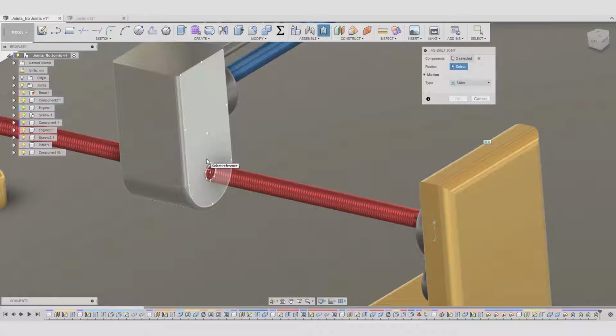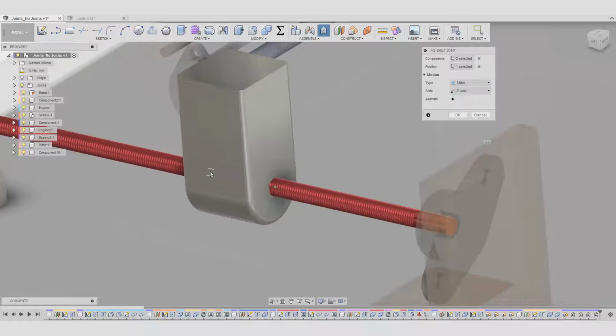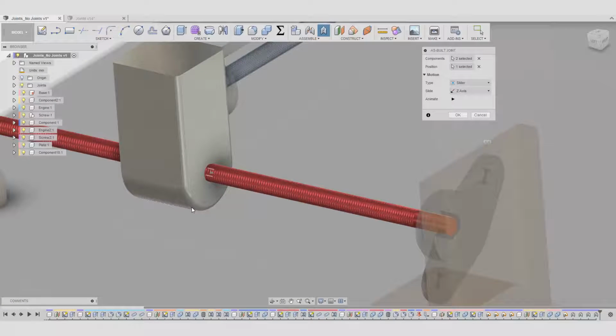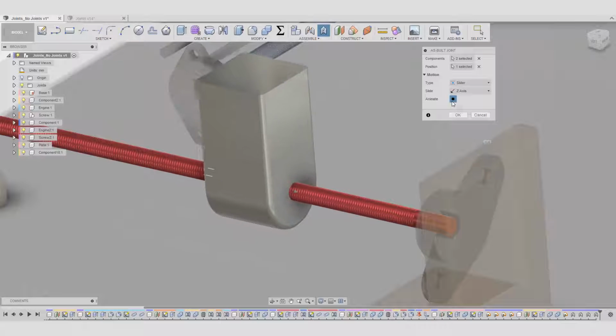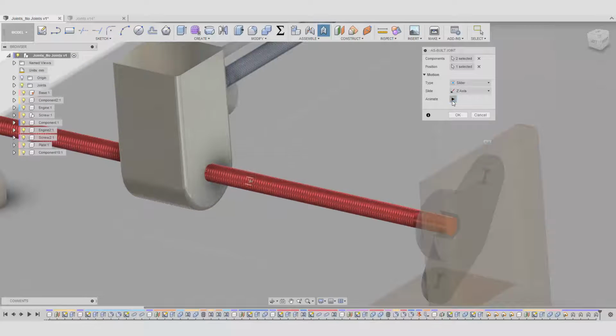So what you can do, press the control button. I think on the Mac it's going to be the command. And then everything freezes. As you can see, I'm moving the mouse anywhere I want. And then I can choose, for example, you see the X here in the middle. I can choose it, and that's it. So remember to use the control if you want to get to a point where it's difficult because it's overlapping with another part or something like that. Just press control, and it's going to freeze everything, and then you can choose the point that you want. Okay, so you can see here we can animate it again. Voila.